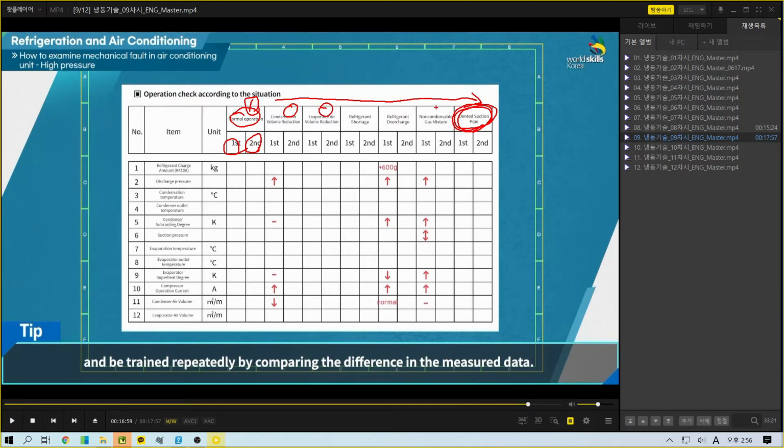So after pinching the pipe to make the dented pipe, it is not possible to proceed with other fault finding tasks after that. So it is better to write the test sheet for pinching the pipe at the very end of the training. I recommend that the training about the mixed-in non-condensable gas fault should be done before the dented pipe fault part.